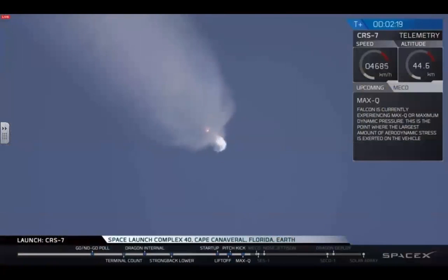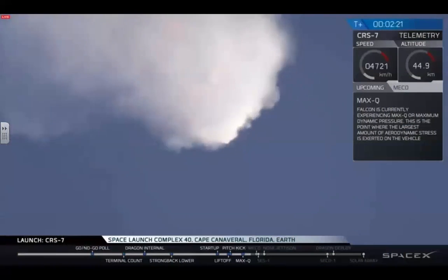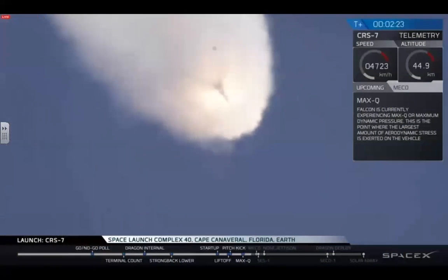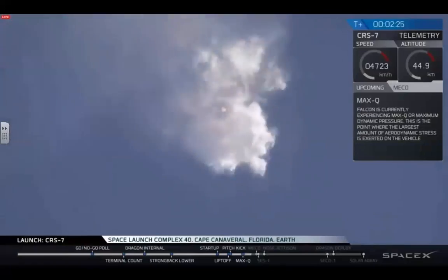One of the things about this is if you want to get high thrust, you need to have high chamber pressures. If you want high chamber pressures, it means you need high fuel pressures, and that means you need high tank pressures. And if you want high tank pressures, you need to have very, very strong tanks, otherwise the tanks will burst. If you want to know what happens when a fuel tank bursts, take a look at the two SpaceX failures. Although they don't use pressure-fed engines, they still pressurize their tanks with helium.